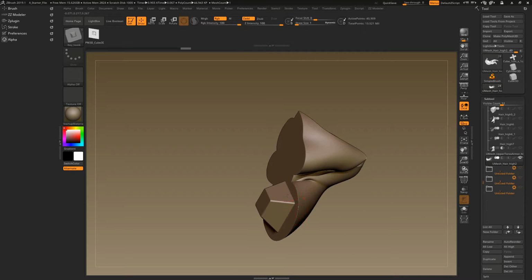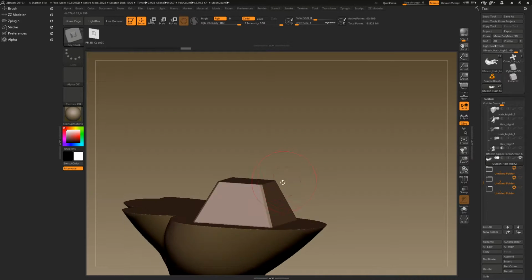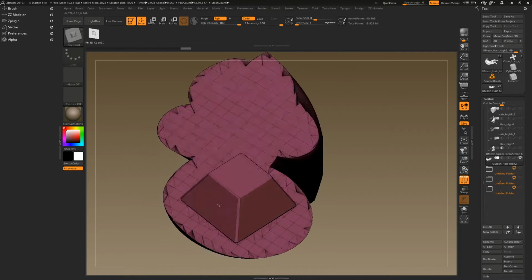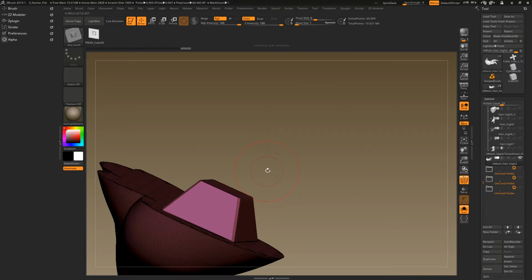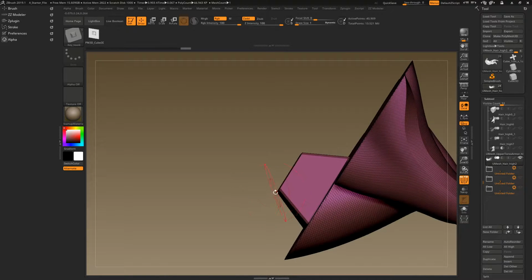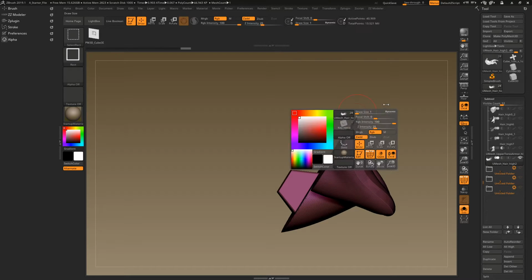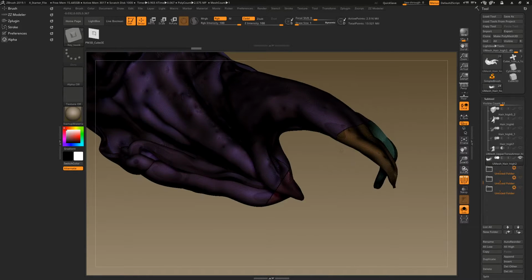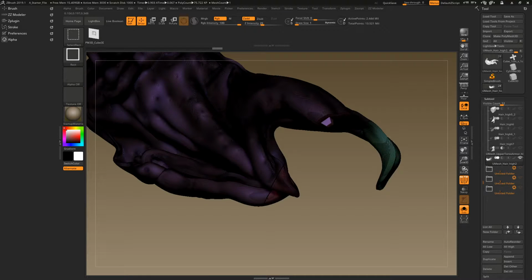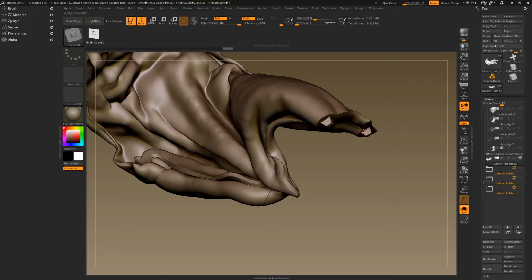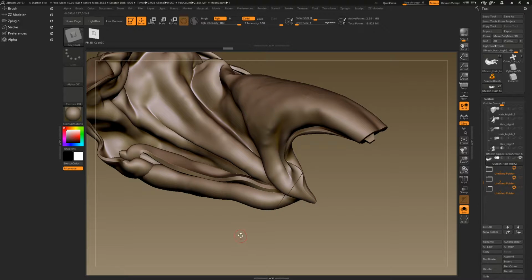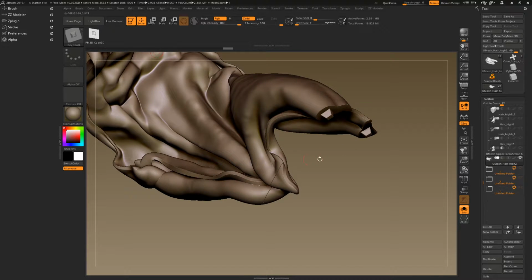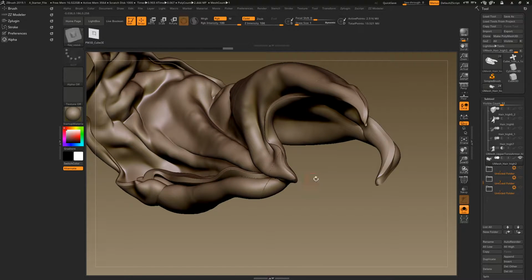Now this is going to get attached to the body. To make everybody's life easier when we go to make this a final piece, I'm actually going to push this edge. I'm going to grab this whole edge and slide it over because I'm only looking for a partial alignment. Since this thing is going to swing around, like I said, like a door hinge from these 2 points, I want to make sure that this guy's a little bit more on the sloppy side, because you're going to use a binder or a glue, an epoxy or something like that, to sort of close them up and tighten them and make them all work together. So it's really just figuring out what the best result is.